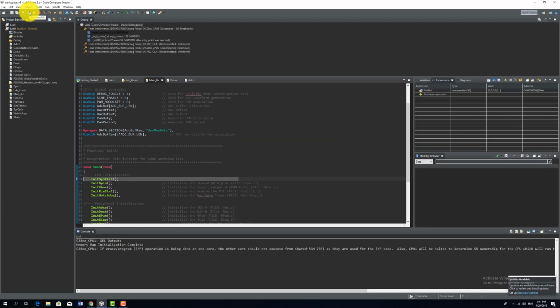We can just wait for a few seconds. Then after we debug, make sure that the power cycle in this activity will be using the EMU boot SRAM. So we have to double check here. So just click the script and then EMU boot SRAM.